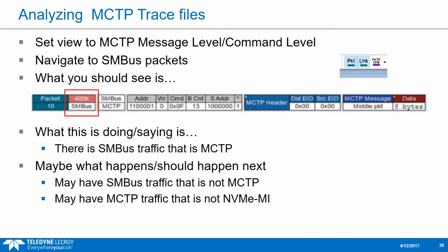And the fields you can see on the right side are defined for the packet that's being sent. This is just a close-up of what the script looks like. So you can create a trainer script that does either SMBus, as the first example there, or basically the same message being sent out over a PCI Express vendor-defined message. Remember, these MCTP and NVMe MI commands are higher layer than the physical medium. And the compliance testing is based around scripts that look like this.